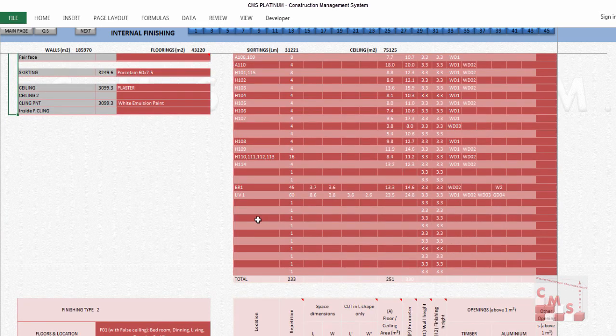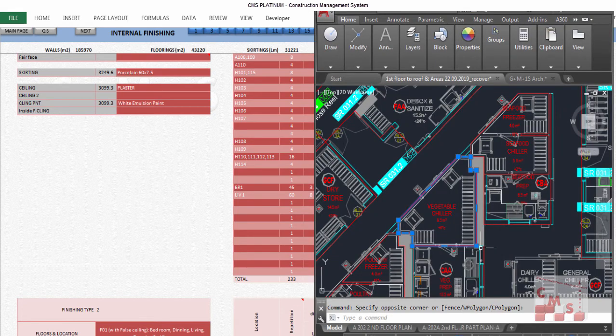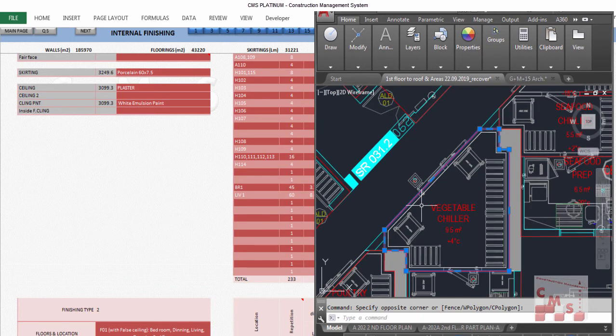Now we already talked about in case if the room is ordered length and width, and in case of the room or the space have L-shaped room. The balance now in case of the space have an unordered dimension, like this room which not have an ordered dimension. So by very easy way we will draw a polyline like this, order of PL, and we'll start to draw the polyline around all the internal wall like this way.